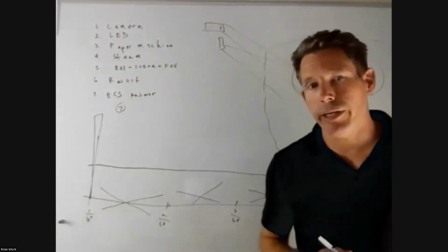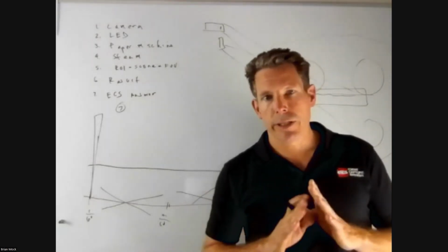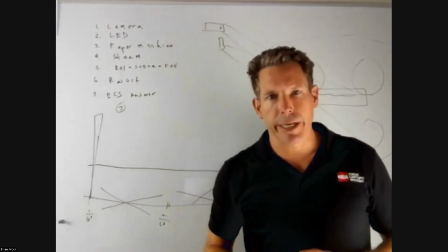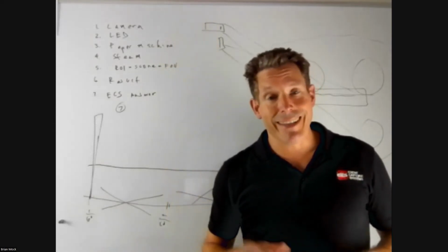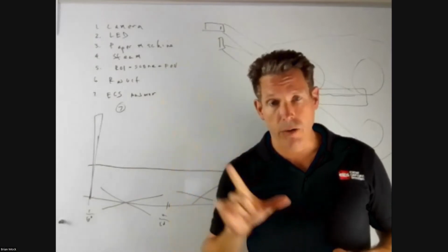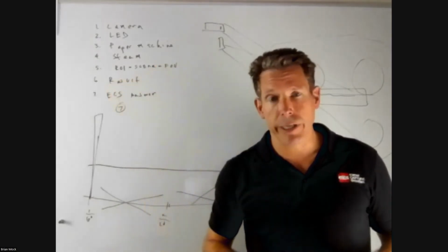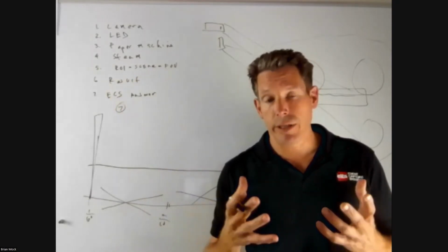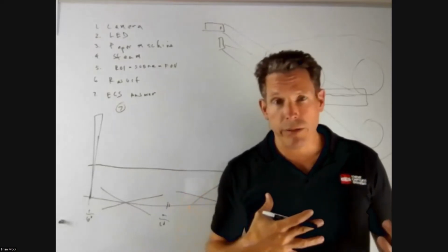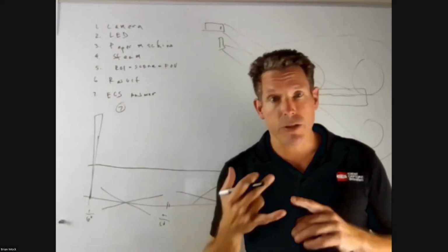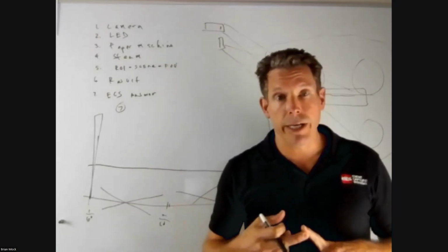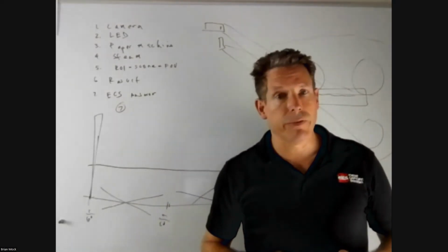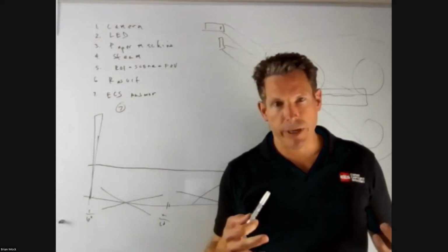So what happens when you take a monochromatic light source, send it up to a brown board, and that reflects back to a black and white camera? That brown board, because it's being hit by monochromatic light, then bounced back to the black and white camera, appears white to the chip. It creates a much higher degree of contrast. Even if you get the strobing right, you get the chip right, you get the Fresnel light right, and you use a white light, you're not going to get the performance that you get out of near infrared, given the same amount of energy and the same setup.